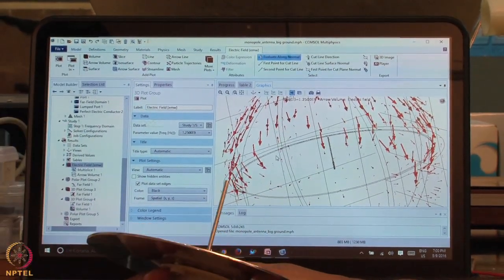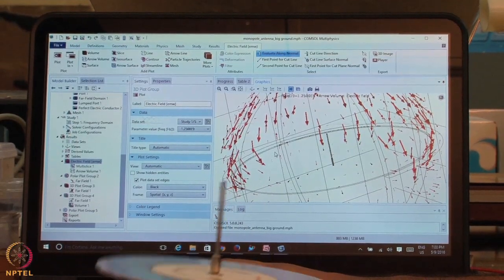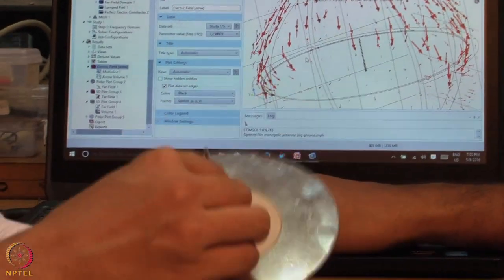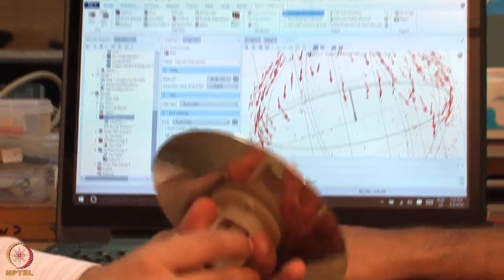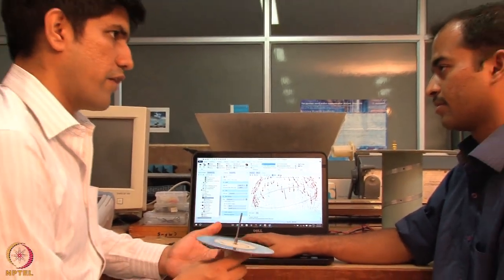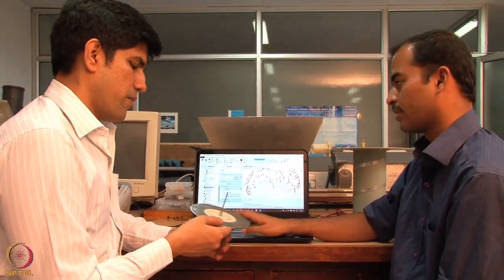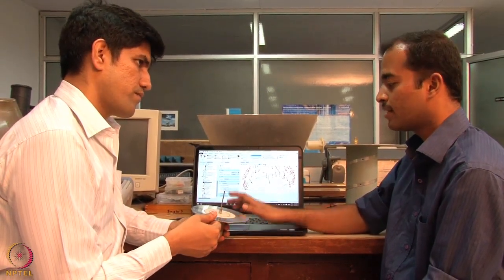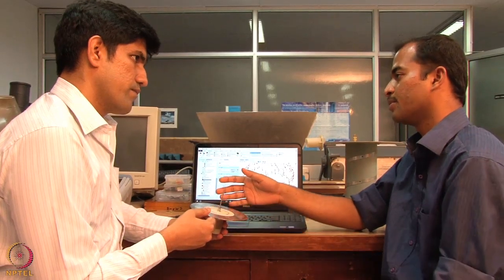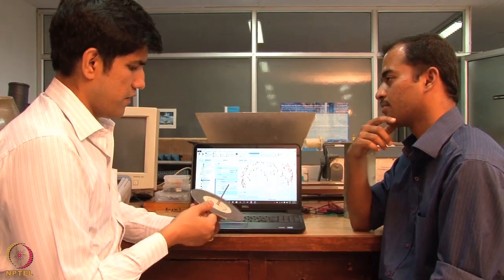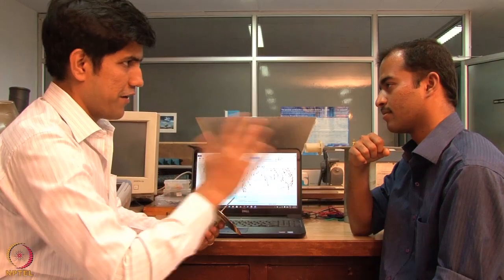Roughly, modeling this kind of antenna, from a design engineering point of view, once we have the dimensions and the right frequency that we are interested in, since it's a frequency domain simulation, it doesn't take a long time. No, not long. But what if I'm interested in doing a broadband simulation? For broadband simulation, I think the geometry itself has to be a bit modified. So that is like a research topic. Okay, so this is a kind of focus for antenna engineers to think about.